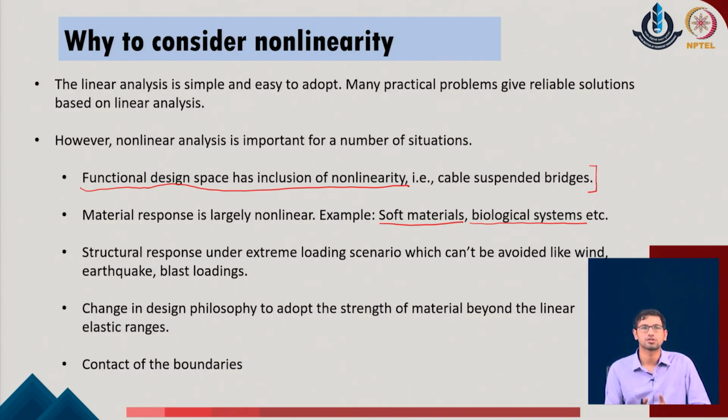If we want our structure to remain only linear under the application of these catastrophic effects, probably the design will become so uneconomical, it will become such a large section of the designs which will not be feasible. So, to make the system responsive as well as flexible enough to undertake these load scenarios, we have to adopt the nonlinear analysis in the given system.